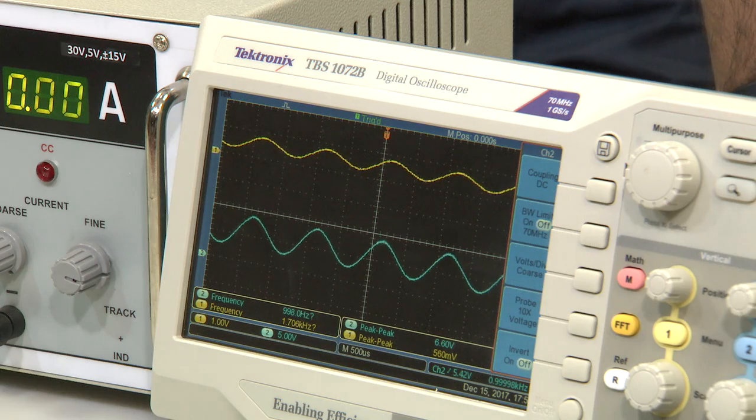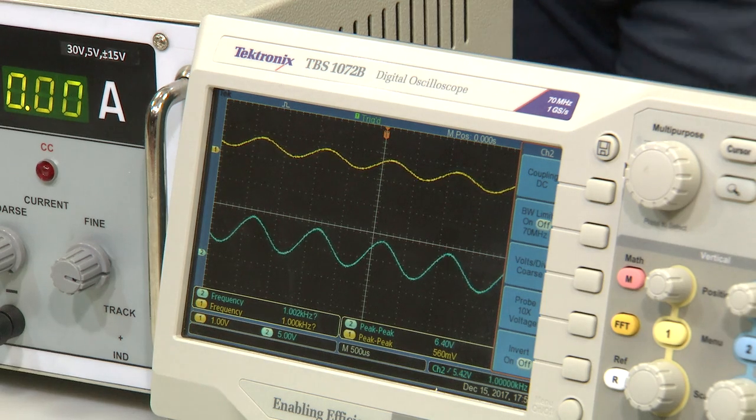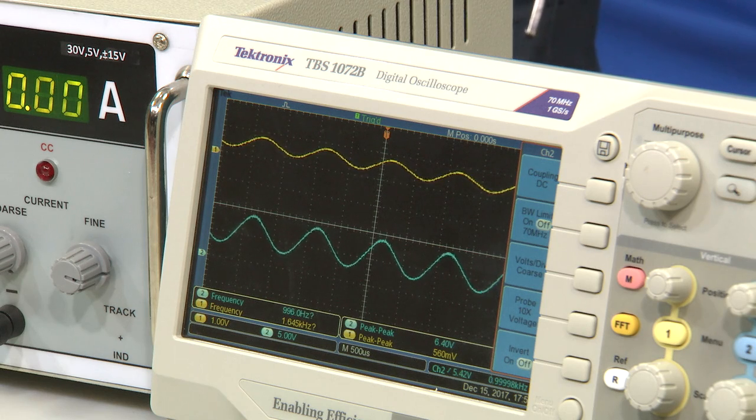So, why is there a change? We calculated about 5.5 volts should be at the output, but when we see it in the oscilloscope we find that it is around 6 volts, right. That is because the resistor values that we are using, your 10 kilo ohm and 1 kilo ohm, may not be exactly 10 kilo ohm or 1 kilo ohm. Even a change of a few ohms will change the gain, right. So, it is extremely important when we use the circuit that you measure the resistance of the resistor, and then you understand theoretical and experimental calculations.